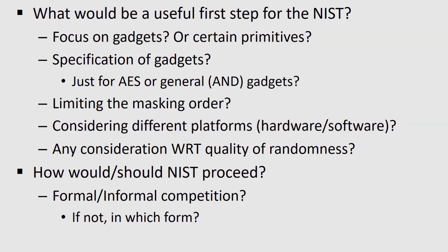One thing that I want to raise is whether we should consider making larger gadgets than just Boolean functions, or not just two-input AND gates, I mean larger nonlinear gates. I understand your concern, FX, that depending on how you implement, for example, the AES S-box, you may end up with either many gadgets in series or many gadgets in parallel, depending on the way that this box is realized in Boolean form.